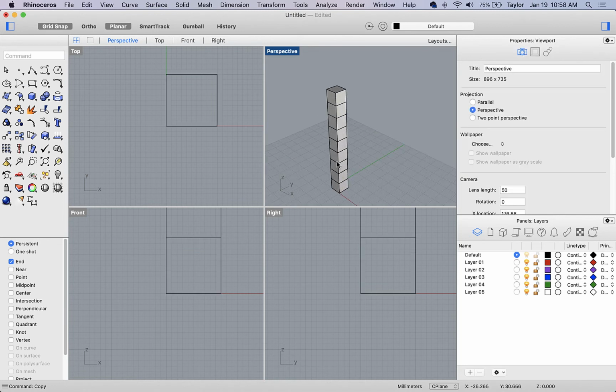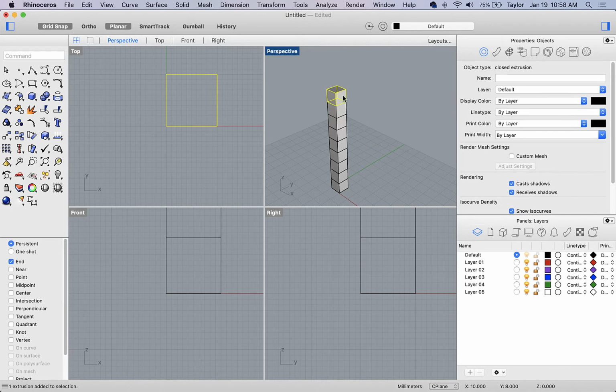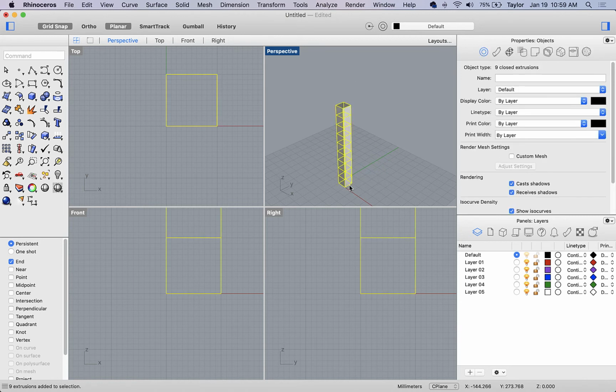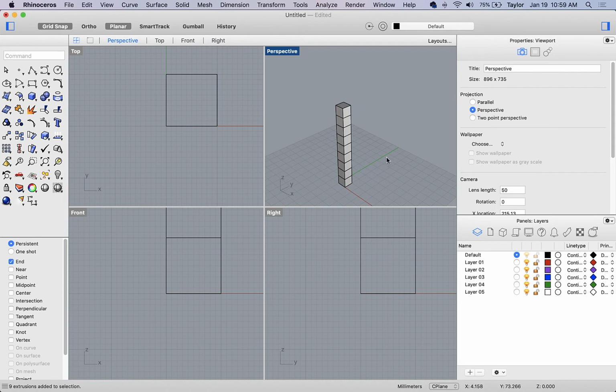And I suppose what I should also mention now is how I've been moving around this space. So when I take the left mouse button, I can click on individual objects and get some information about them. I can also drag a box. So if I drag from the left to the right, I can make a selection box like that. However, if I just partially touch an object, it will not be selected. So that can be useful for picking an object out of a group if you don't want to bring everything with you. If you do want to bring everything and you want to just be kind of sloppy about it, you can drag from right to left, and then anything you touch does become selected. So that's the left mouse button.